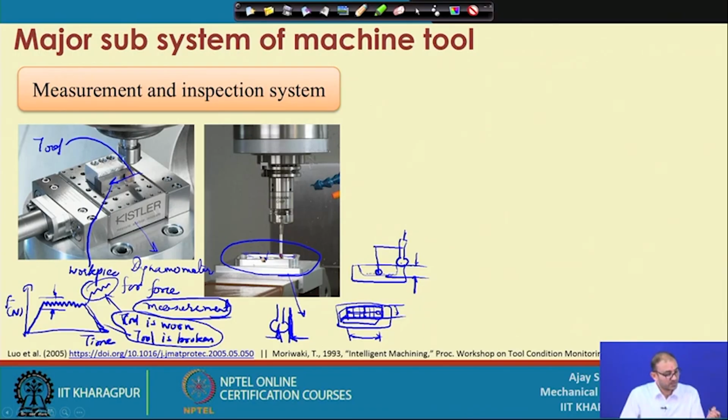So, these systems are very useful and important, because once this is done, you do not need to remove the workpiece. By chance if there is some error, then you repeat the operation and get it done. If you remove the component, your work is very high, because again you have to realign exactly at the same location. If that is not possible, then you have to do all the calculation again, because you have to find the work location, find where you are going to start the operation, find the reference position, then find out the Z axis compensation, that means you have to find a surface with a Z0, and only then can you go depth-wise, correct.